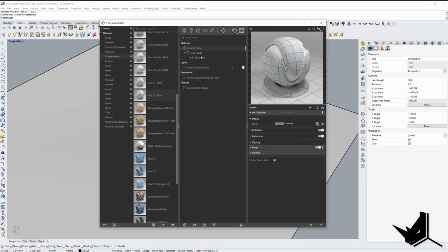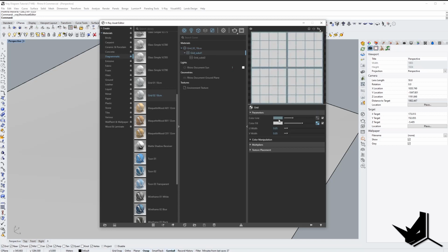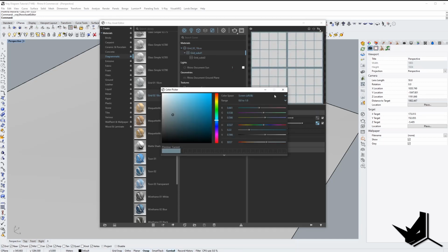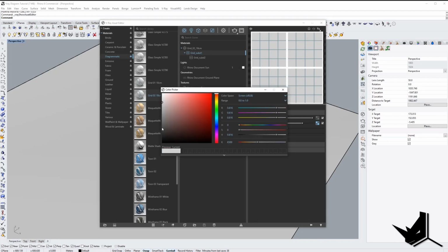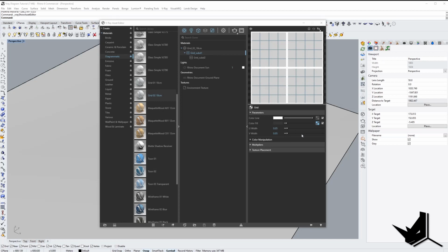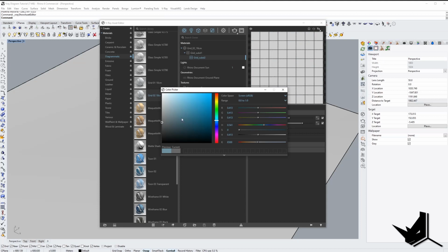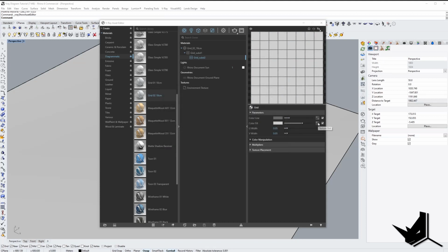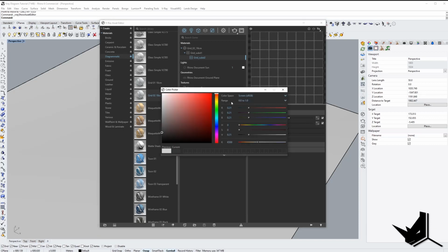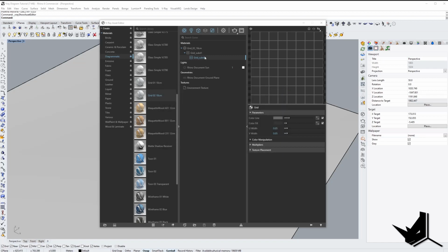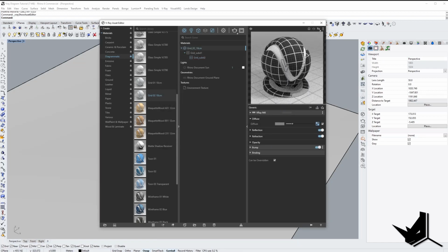You can see here how we have white lines and we have blackish tones for the fill color. So we will try to replicate that, and we simply need to go into first grid, and then let's change this line color from blue to white, like so. And this fill color is supposed to be a little bit darker, something like this. And we can also do this here in this area. So let's create something like this, and the fill color here should also be black, so that we get that effect of the material looking just like we have it here.